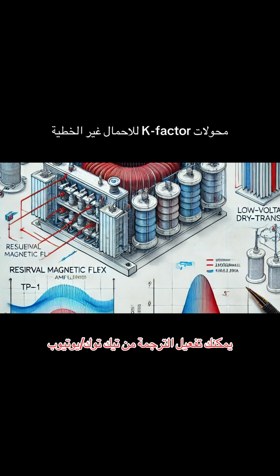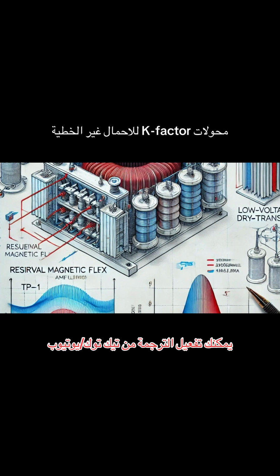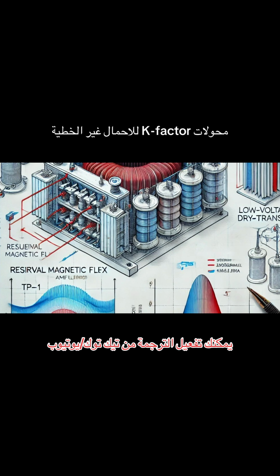It's fascinating to see how the increasing reliance on electronic devices has driven the need for these higher K-factor transformers. Now, the paper makes a couple of really important points that I want to highlight for our listeners. The first one is that the K-factor rating is a measure of a transformer's ability to survive the heat from harmonics, not to eliminate the harmonics themselves. Can you expand on that distinction?